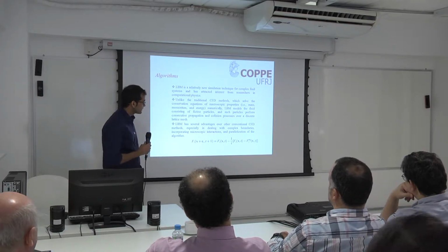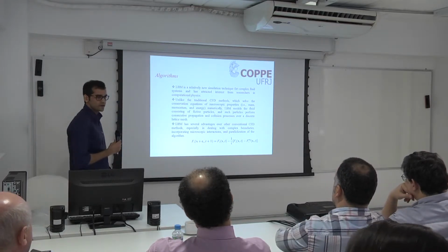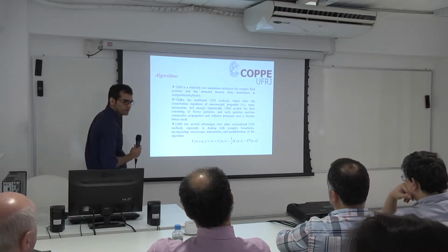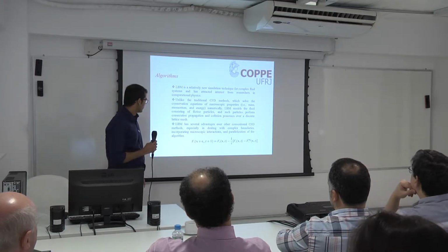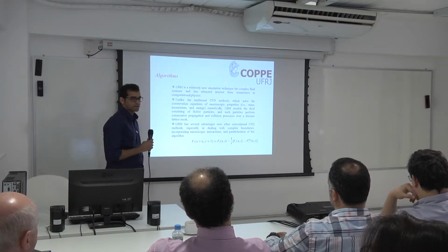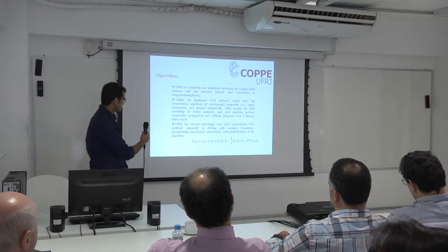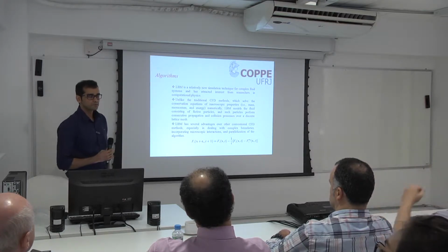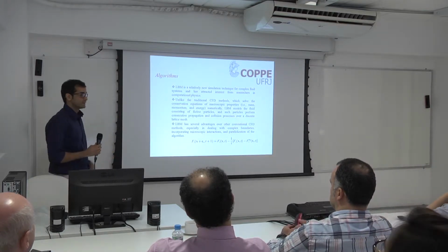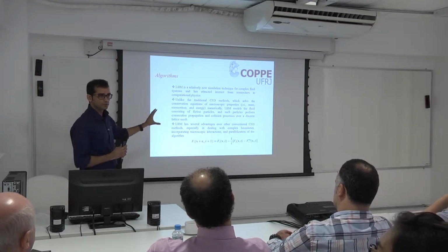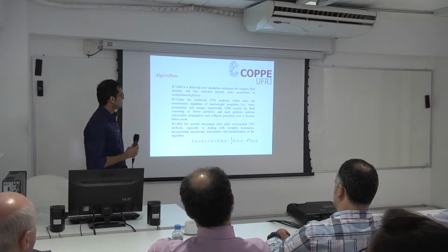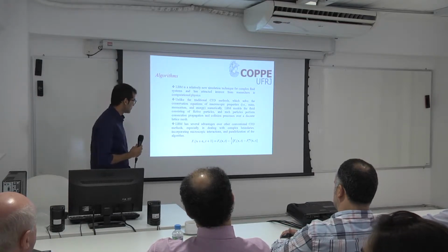Lattice-Boltzmann has several advantages over the conventional CFD methods, especially in dealing with complex boundaries and incorporating microscopic interactions. Microscopic interactions are the interactions between the fluids, the particles, because the fluid has a particulate nature, the model is a particulate model. And the parallelization of the algorithms.